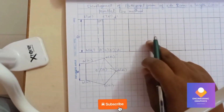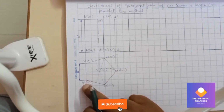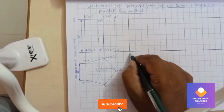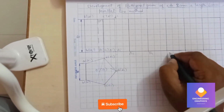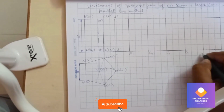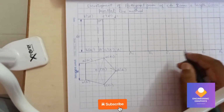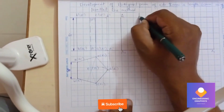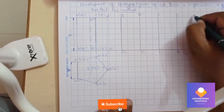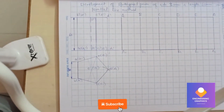Okay, so 5 faces, you can see 1 2 3 4 5, each of the faces having the same edge length of the pentagonal prism. So we will be naming them in capital letters, that is A1, B1, C1, D1, E1, and A1 again, joining with the same face. Same way, we'll write for the top also capital A, B, C, D, E, and A. So this is nothing but the development of this pentagonal prism using the parallel line method.